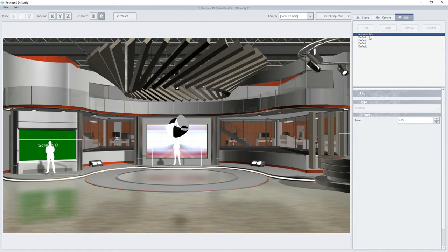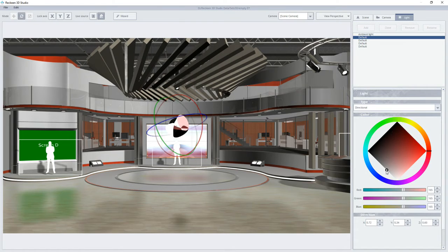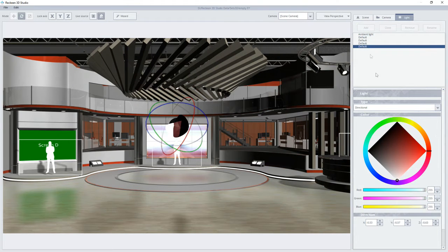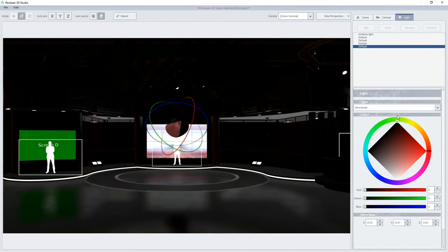First, I will set all the lights' color value to 000, which means I will turn the remaining lights off. We will immediately see that some of the materials used in the set, such as white stripes, are still highly visible. These are specific emission materials. We can additionally light them up, but they will still be visible when we turn the lights off.